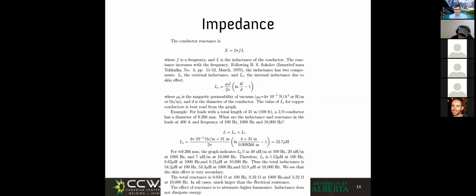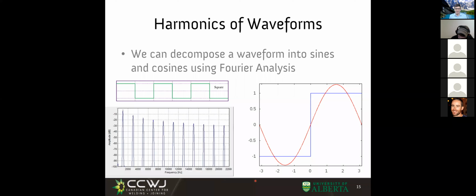And we work through these numerically too. And here we have an example about how a square wave, in theory, has a low frequency. In reality, the square wave is made out of a combination of infinite sines or cosines that have very high frequency. And as we chop off the high frequency components, we destroy our square wave, and we end up with something that is close to a sine wave. And all the sharp edges, that are good reasons to have the sharp edges, are going away.